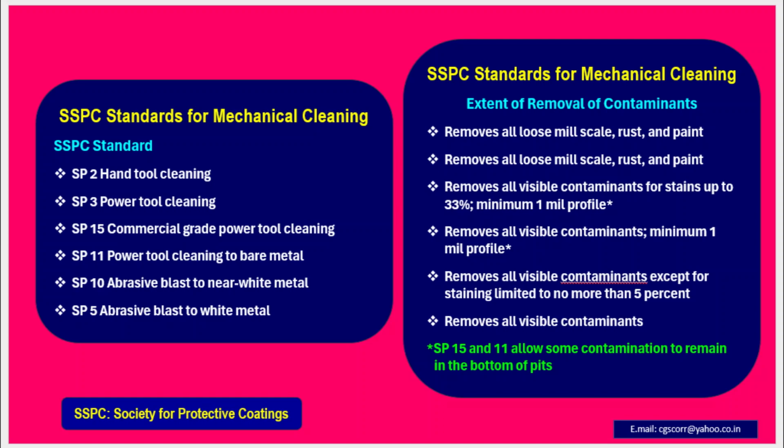SSPC standards for mechanical cleaning. What is the expansion for SSPC? Society for Protective Coatings. They are SP2 hand tool cleaning, power tool cleaning, commercial grade power tool cleaning to bare metal, abrasive blast to near white metal, and abrasive blast to white metal.